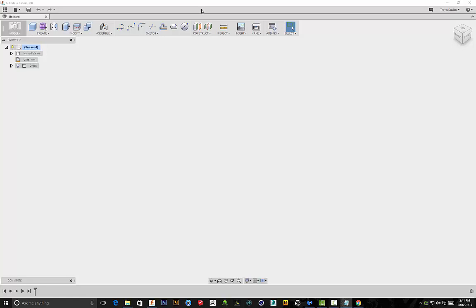So what we're going to be doing is creating one sketch profile. The reason why I'm going to be creating one sketch profile, I actually saw this technique online, is that when you create one sketch profile, it enables you to select different points of your loft, which will allow you to dynamically change the shape of the loft that was created.